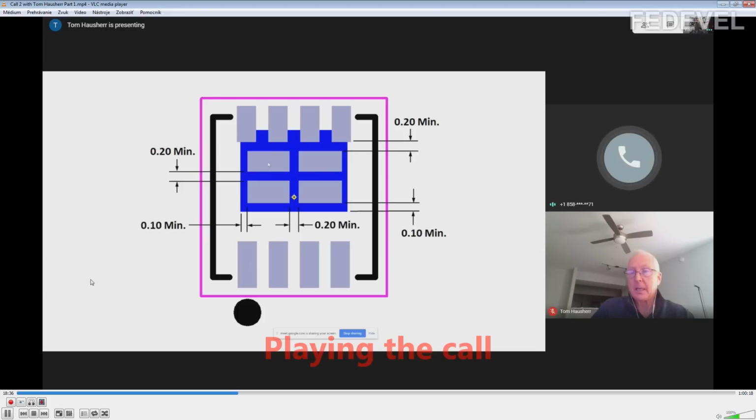That's because if you put 100% of solder on the thermal pad, number one, there's nowhere for that solder to go, nowhere for it to move. And the part will float on top of that solder. Could you imagine having a full paste on a thermal pad and then going through the reflow oven and the part floating on that thermal pad? What will happen is the part would teeter-totter against the thermal pad, and the other leads, pin 1, pin 2, pin 3, and pin 4, would not make any contact. There would be a little gap between the pattern and the part, because the part would tilt because there'd be too much solder on the thermal pad. So we reduce the solder on the thermal pad so it can flow, reducing the thickness of the solder so the part can lay flat on the board.